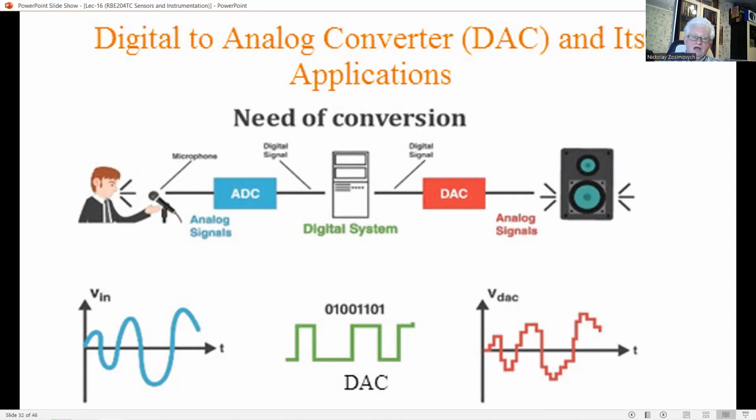For example, the off state of a bistable logic element, or absence of a voltage pulse, or low level of a voltage signal, or even no change in a voltage level can be represented as a binary zero, right? Conversely, the on state of a bistable device, or presence of a voltage pulse, or even high level of a voltage signal can represent binary one. The combination of these bits, which forms the digital word in the DAC register, will correspond to a numerical value of the analog output signal.